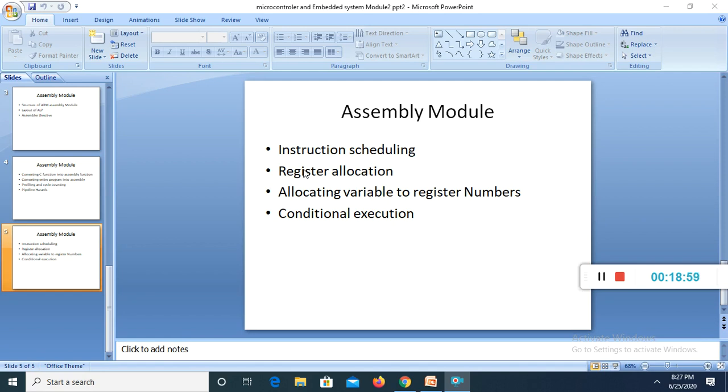Let us see how to allocate registers when writing assembly. Suppose we want to shift an array of n bits upwards in memory by k bits. For simplicity, we assume that n is large and a multiple of 256. Also assume that 0 is less than k and k is less than 32, and that the input and output pointers are word aligned. The C routine shifts bits as follows.